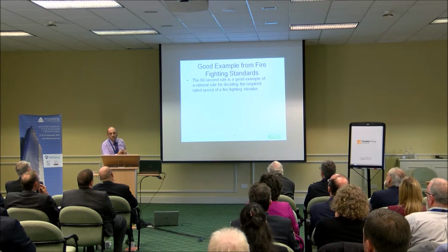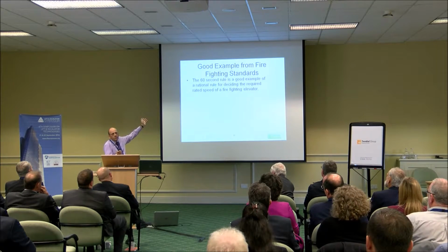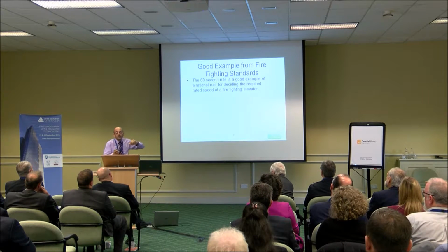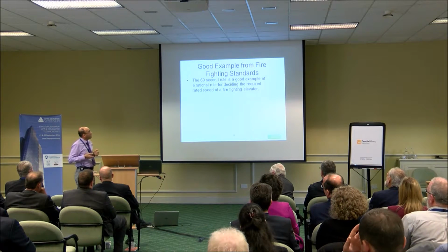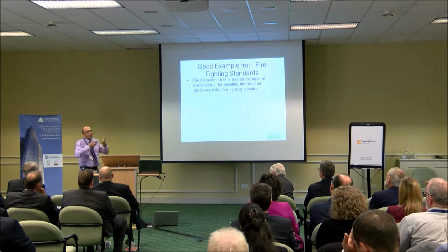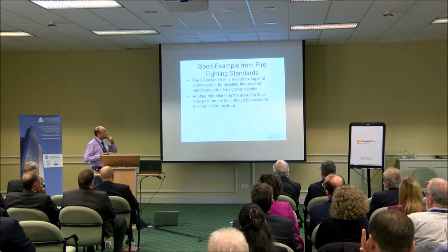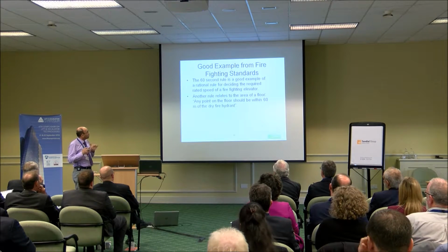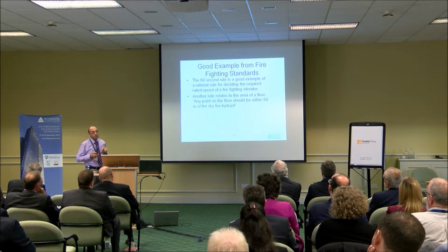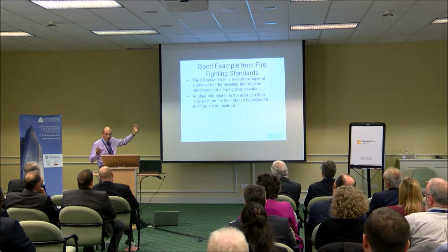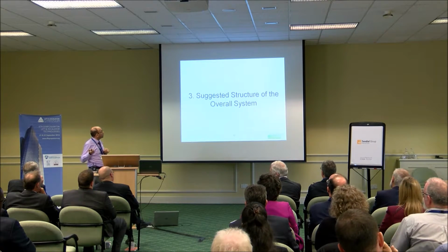I like these examples from fire engineering, and Adam or others maybe can confirm them. For example, a nice example on selecting the speed of a lift for firefighting is the 60-second rule. The lift must travel between terminal landings, including delay for acceleration and jerk, in 60 seconds. And there is a rationale for that. So for the firefighter, he can get to the point within a certain period of time. Another nice one, which depends on the length of a hose. If we have a fire hydrant on a floor, then any point on the floor must be accessible, must be within 60 meters of that fire hydrant. So these are nice rules, rational rules, which you can see the rationale behind them, the reasoning behind them.